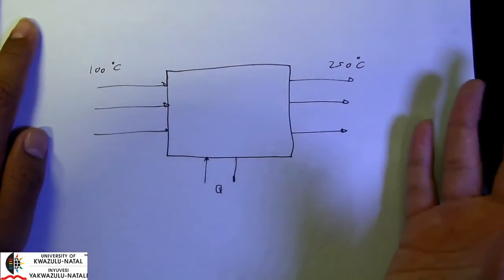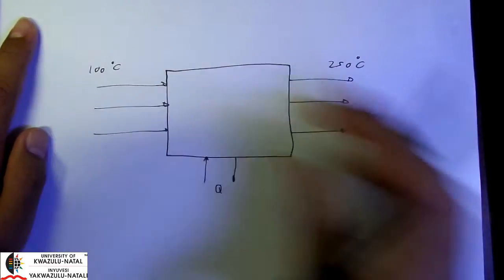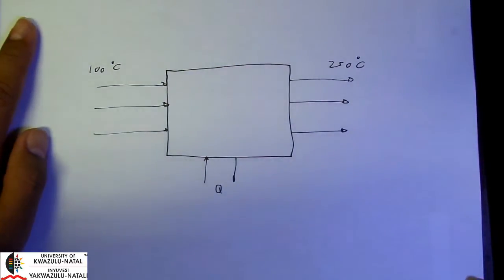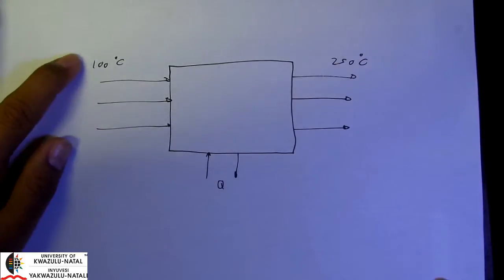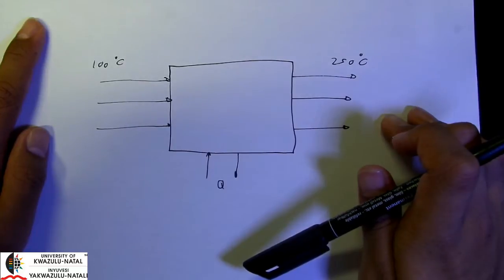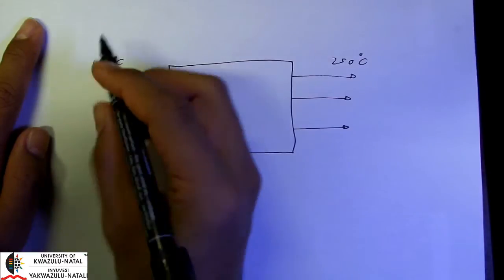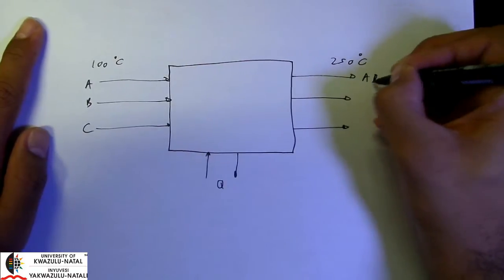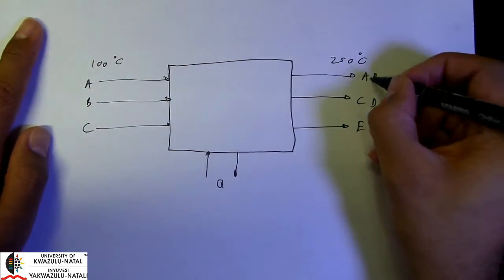And how much heat will we need to remove? It's simply the difference between our output streams and our input streams. And remember that we are expressing our enthalpies in terms of a reference. That reference could be 100 degrees, it could be 250 degrees, it could also be 25 degrees. Now what's important is that, let's say we have various species coming in, and various species coming out.